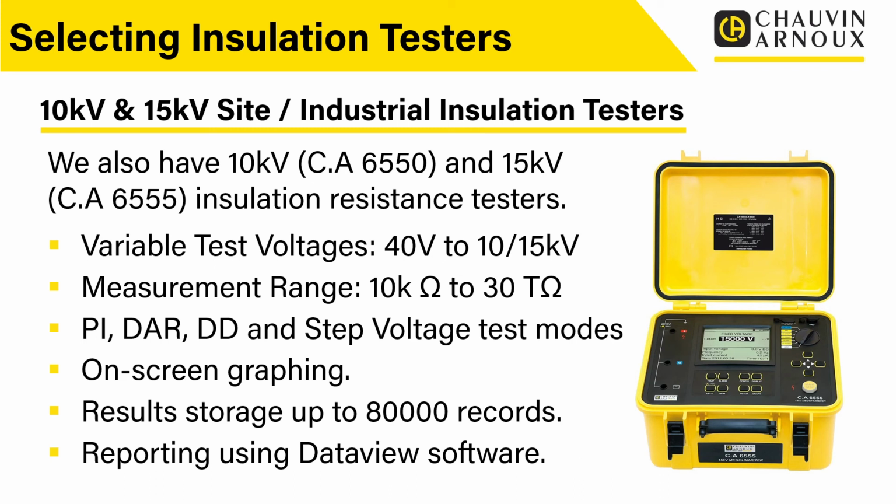And these have all the features that I've just talked about with the 5 kV products, but they also add a few extras on as well. And obviously the increased test voltage is part of that. So we have variable test voltage, in this case from 40 volts up to 10 or 15 kV. We've got a measurement range from 10 kilo ohms all the way up to, in this case, 30 tera ohms. We've got the ability to do all the usual stuff, the PI, DAR, DD and step voltage test methods.